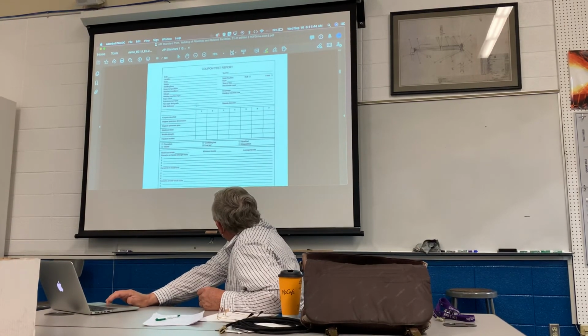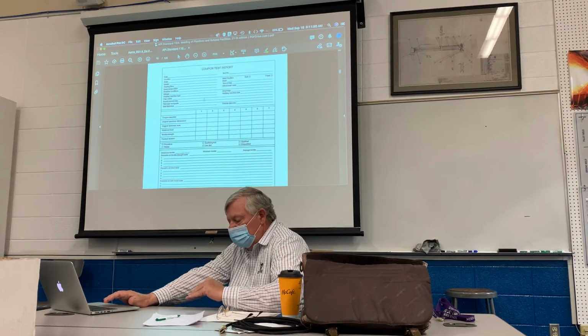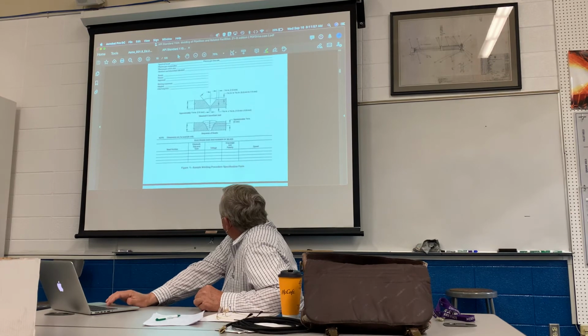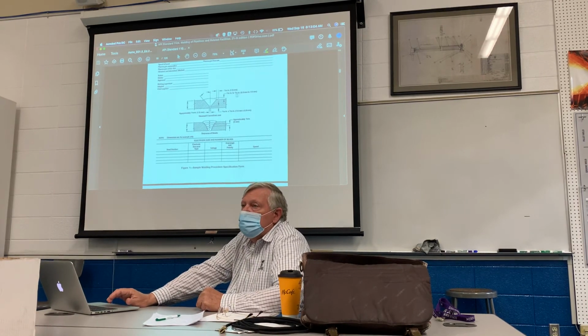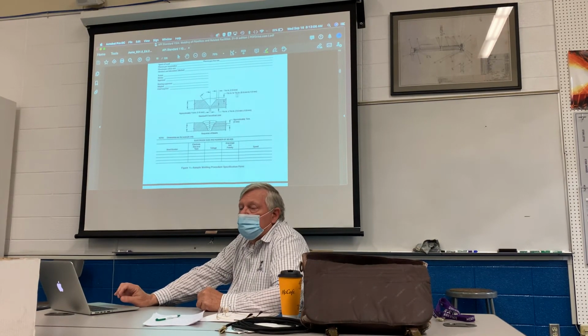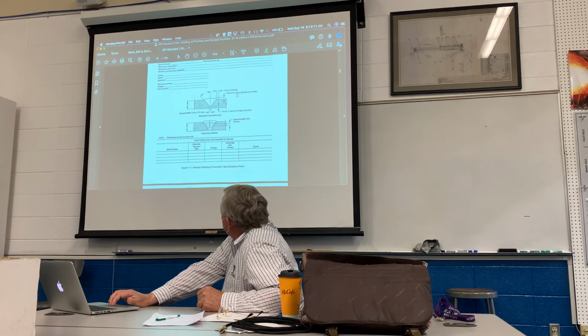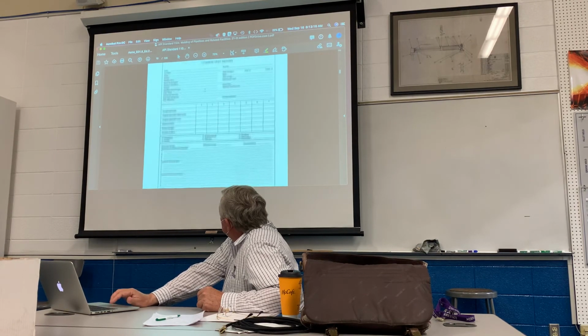So reinforcement size is going to deal with excess reinforcement or concavity, how big was the reinforcement? And if you have on this drawing right here that it's supposed to be 1/32 to 1/16 of an inch, it better be less than that. Reinforcement better be less than that. So this drawing is going to determine the data that you're going to put there.